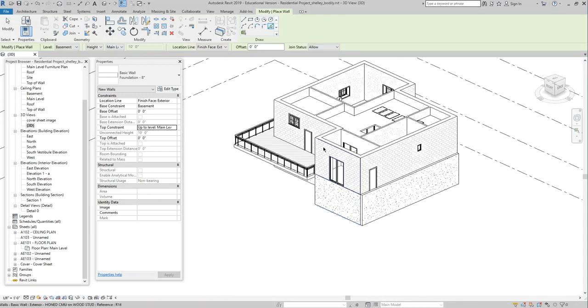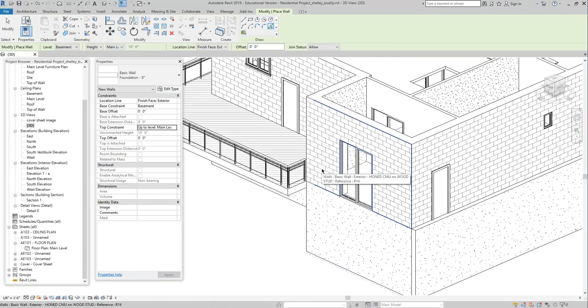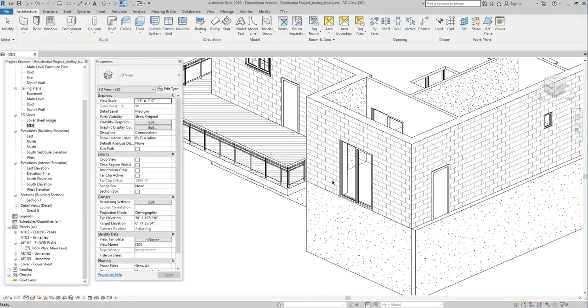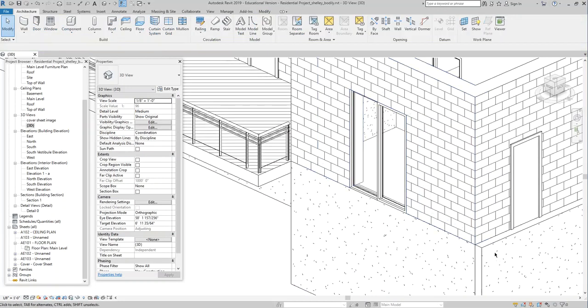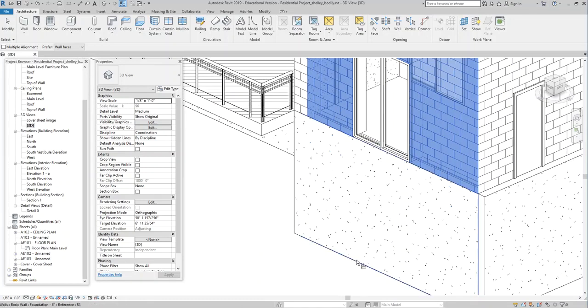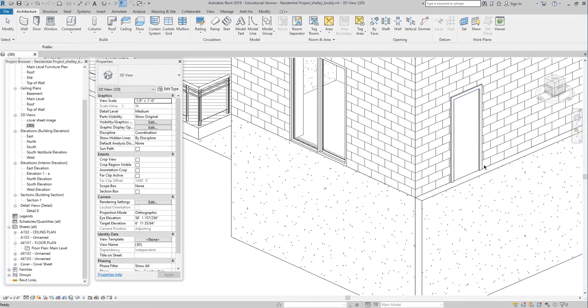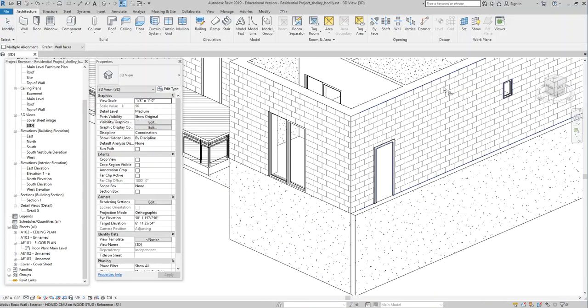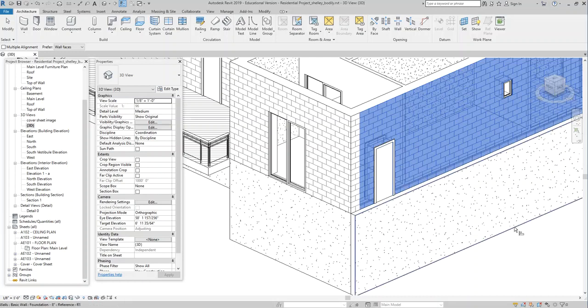And I want to make sure that all these foundation walls are lining up with the outside face of this upper wall. Okay. So right now, it looks like this wall is in line with this wall, but I'm just going to go around and make sure. I'm going to use the align command, AL, and we know that we can align things in floor plan view, but I want to also show you that if I hover over the face of that wall, I can click, it highlights it, and I can come down here and near the boundary. See how I can pick that wall, click, and it just makes sure they're aligned. Escape, align, AL. Pick the face of that wall. I'm going to pick the face of this wall.